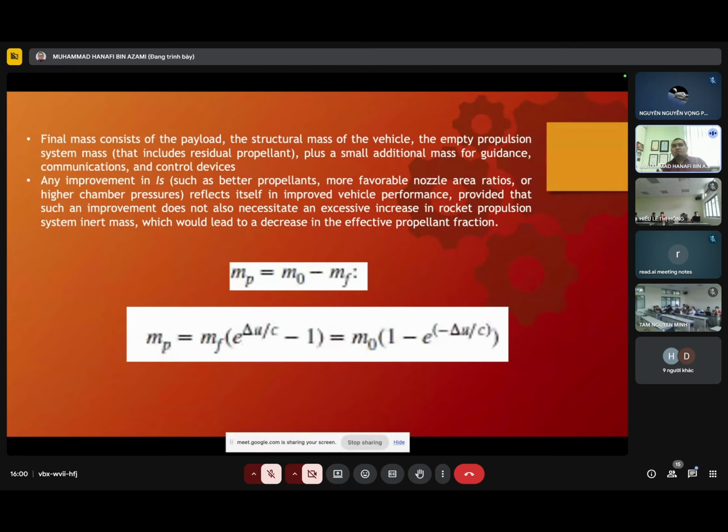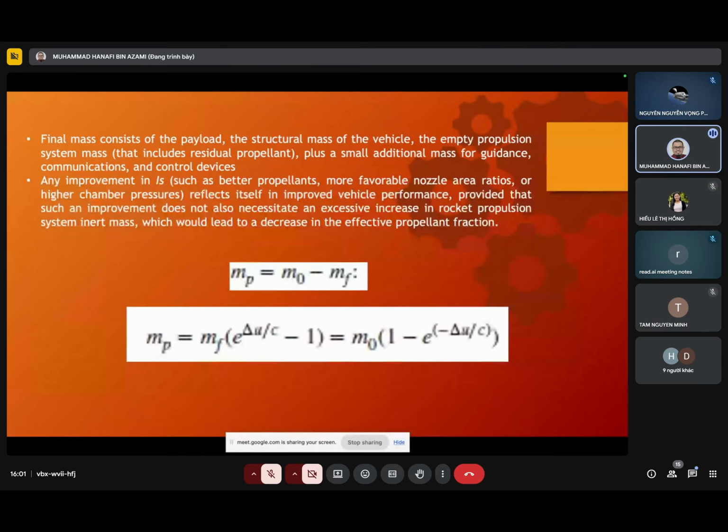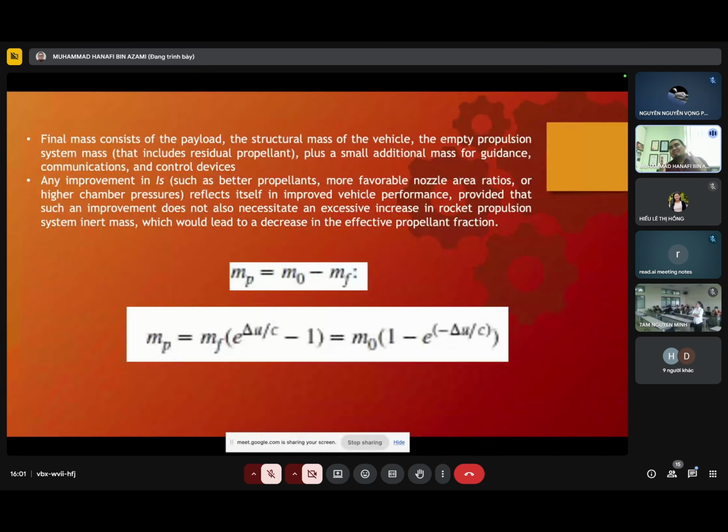If you try to make the angle as big as possible, the gas will separate from the inside surface of the nozzle. When gas separates inside the nozzle, you will lose some of the gas expansion. You will lose thrust, you lose energy. So we want the gas to be fully attached to the surface.